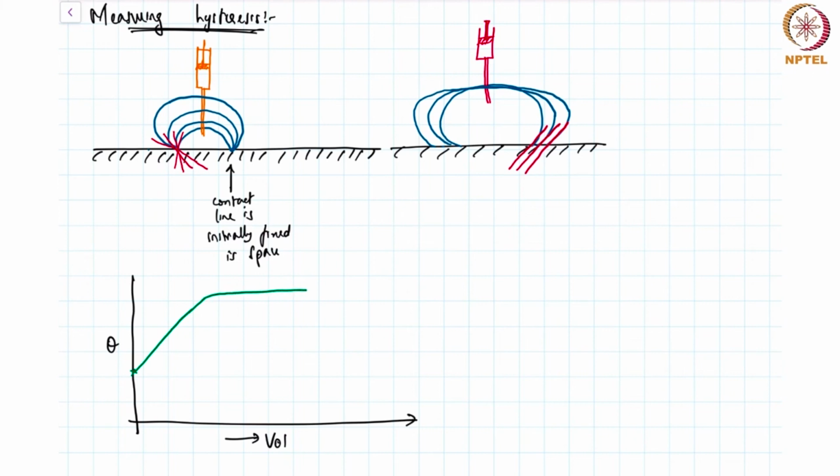Now, once you have reached this, the angle remains constant for a large amount of volume. So we have determined the maximum theoretically possible angle, and this upper limit, we'll call theta A. The droplet front is literally advancing into the fluid, and we call it the advancing contact angle.